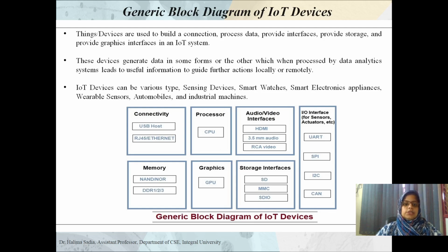However, in I2C we can connect multiple slaves to a single master device, and we can also have multiple masters controlling single or multiple slaves. It is really useful when we want to have more than one microcontroller logging data to a single memory card or displaying text to a single LCD.